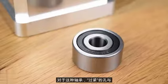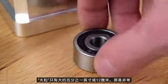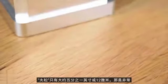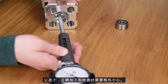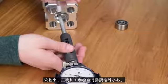For this bearing, the difference between a bore that is too tight and one that is too loose is only about 5/10,000ths of an inch, or 12 microns. That is a very tight tolerance, and it requires some care to machine and inspect correctly.